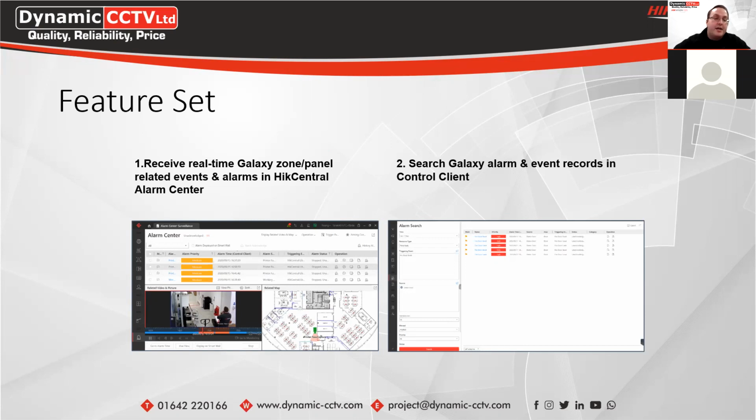And you can actually relate that to a camera as well. So if an alarm or an event's triggered, it'll relate to one of the CCTV cameras using Optimus through CCE. It also allows you to search through the different Galaxy alarm and event records using the control client of CCE, which will allow you to search back and see any events or alarms that have been triggered by the Galaxy panel without having to go into the Galaxy system. You can do this straight from CCE once it's been integrated using the Optimus software for the system.